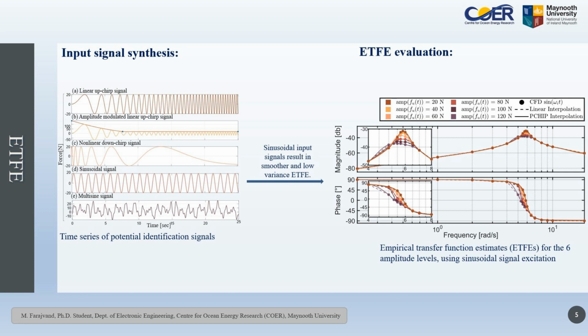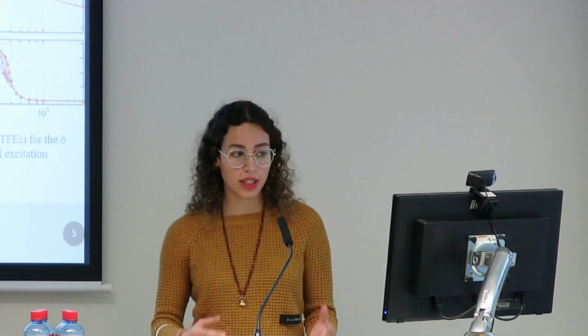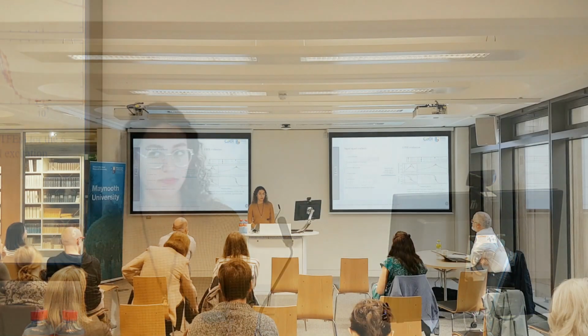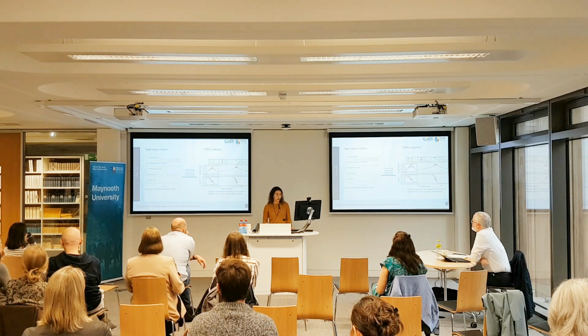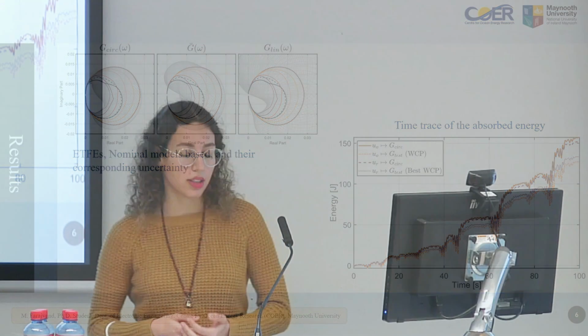Until now, I've done synthesis of the input signal to see how I can build a model where the uncertainty will be low, so I'll have a less conservative controller. Also, the selection of a sensible nominal model is important, and based on the different nominal models that we choose, the efficiency of the control will be affected.